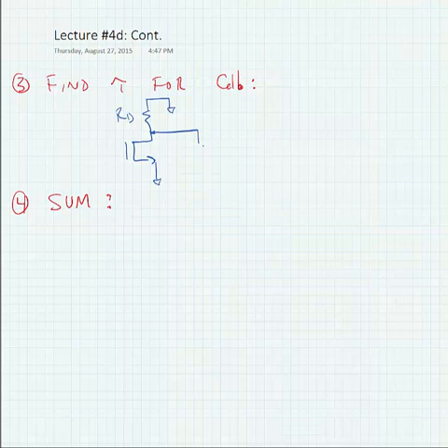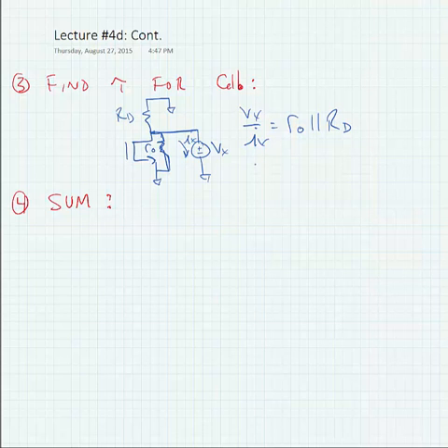We're going to replace CDB with a test voltage source. Measure the current flowing out of it, or into it, depends on how you want to reference it. Now, we know that the output resistance of the transistor is also tied to the drain, so here we have that output resistance. So if we were to measure Vx over Ix, we would find that it would equal R out in parallel with Rd, and hence tau CDB would be the product of CDB and that resistance.